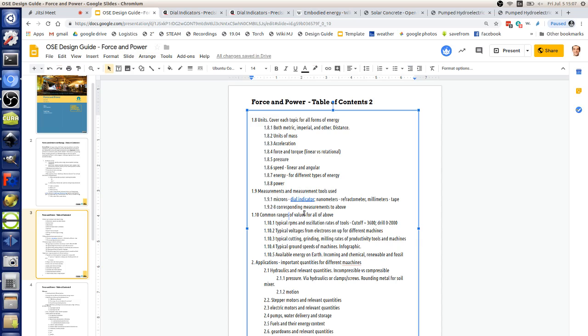It's important to have a feeling for that, because when you're designing a cordless drill and you get an off-the-shelf motor that spins much faster, you're going to have to know how much you have to reduce it to make it go at a useful speed. So you have to be familiar with what a useful speed is. You can picture that in your mind. You have to start getting a feeling for what RPMs are to get an understanding. Otherwise, those are just numbers.